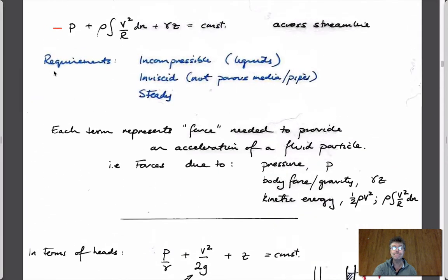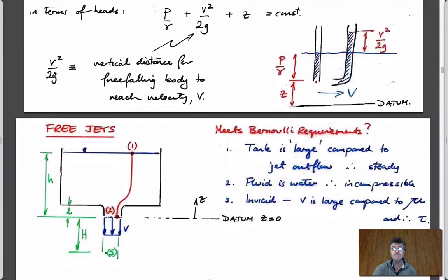All right. What else? So Bernoulli's we know. Be clear about when you talk about conditions. When you're in the flow of the stream, you'd have a velocity, and at a point where clearly there's no flow in this pipe, it has to be stagnant. So if you go into the neck of this pipe, the velocity out here has to be finite and perhaps unchanged from the upstream velocity, but somewhere in this pipe the velocity has to be zero. And so this is the component that looks at whatever pressure you develop in this pipe. And of course, if you were in class today, you realize that the pressure you get is like our Euler number. You kill the velocity and you generate a pressure as a result of it.